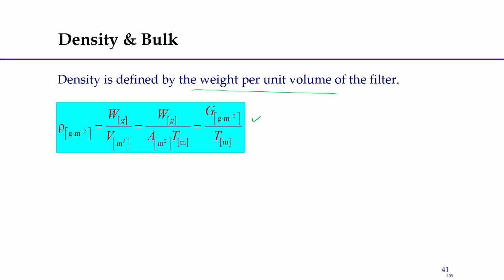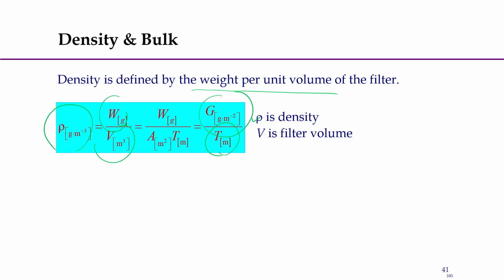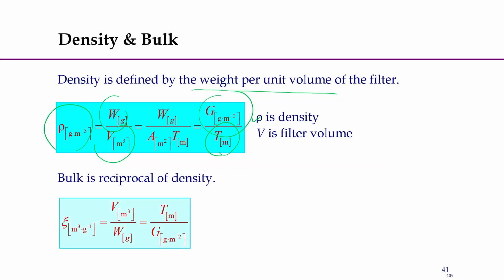This is the density, mass per unit volume. If we get the grammage and the caliper thickness, the ratio will be the density, and from there we can calculate for a certain area. So, bulk is the reciprocal of density. Basically, it is thickness per areal density, that we can get the bulk, which is important.